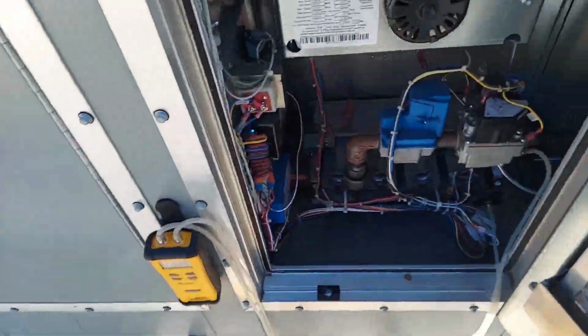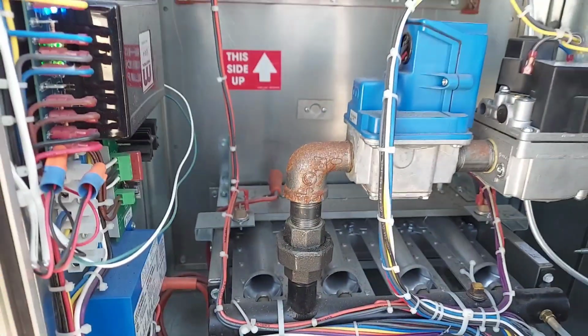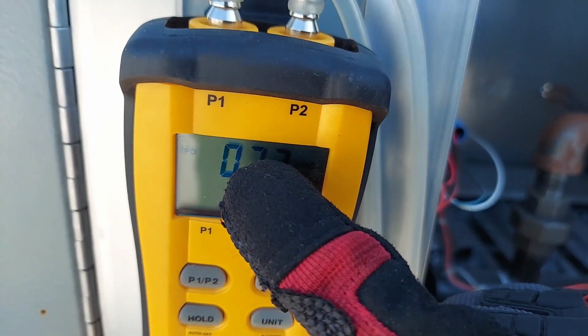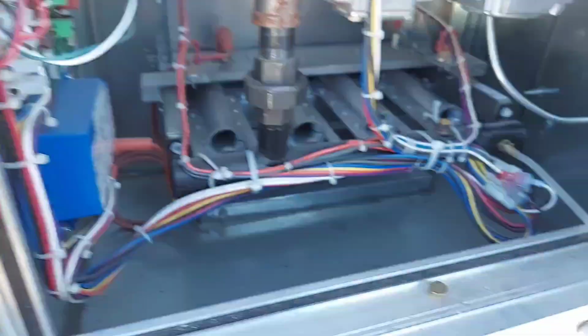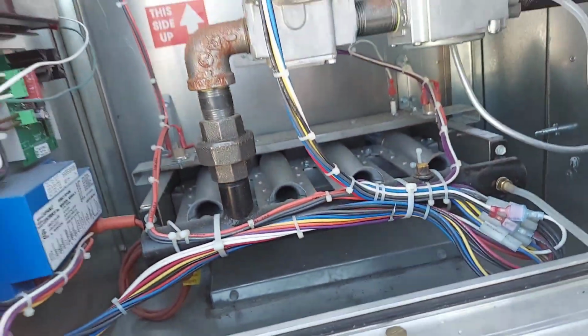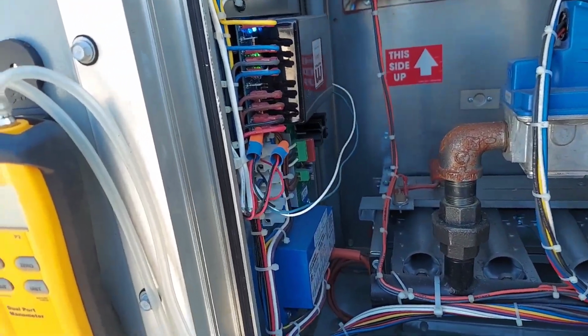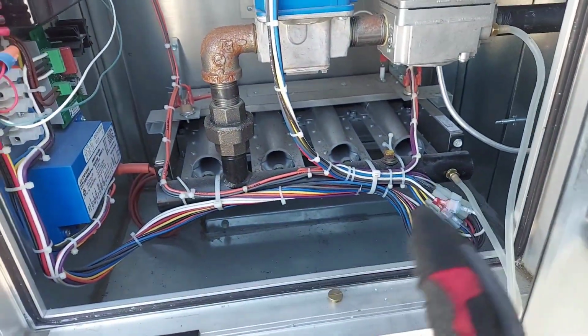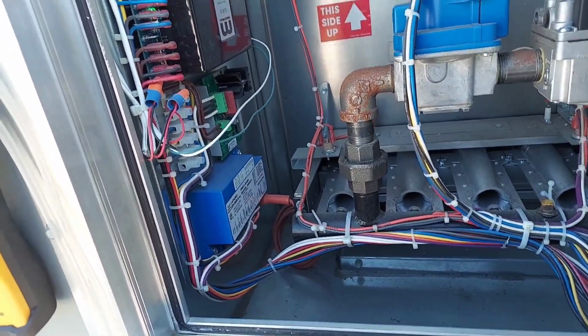So the fan is gonna run. I don't know if the fan slows down if I go to 25? But yeah, it does show right here on my tool. Stock pressure is down, man. Manifold pressure is down. And my flames dwindled. It's a modulating furnace for you, baby. So we go to that, a smaller flame. The flame is tiny right now. Tiny. The furnace in your home can't do this. This is a commercial furnace.